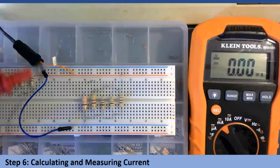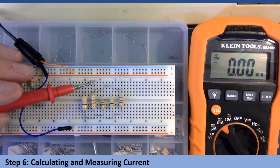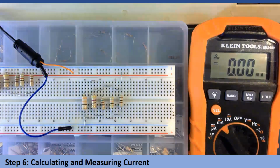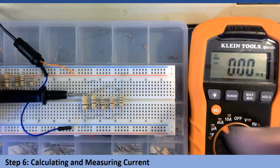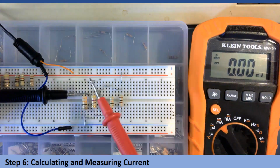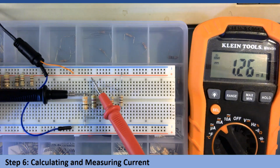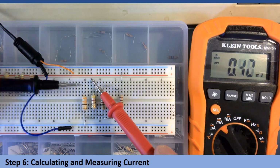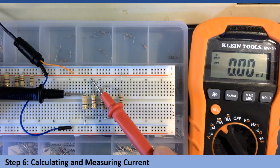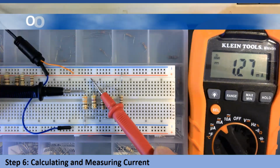I'm going to put my red lead on that hoop, and it's going to go through the power and it's going to end up with the black. So I'll put my black on my most negative, which is the resistor itself. I'm going to take my red lead and put it into that hoop and connect. And now the meter is becoming the current source. And it's putting out about 1.27 milliamps.